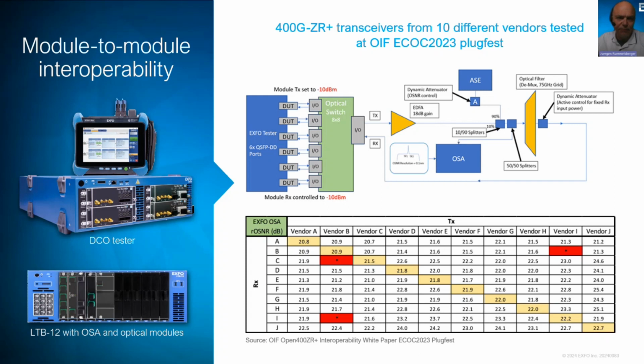And here the traffic soak period was 30 seconds, and the noise steps were incremented by 0.1 dB. And here the ASE source was used as a broadband source, and the attenuator accordingly to increment in the step mentioned.